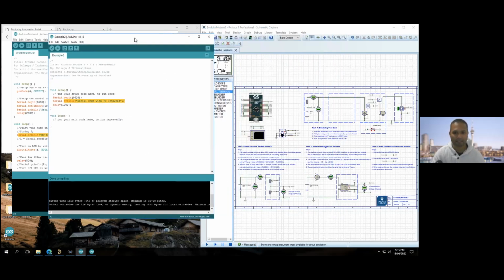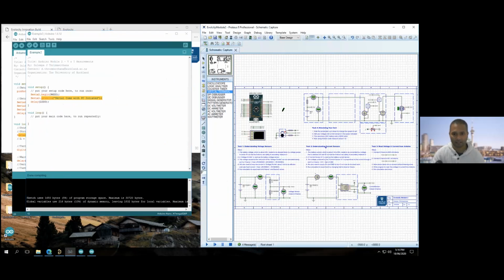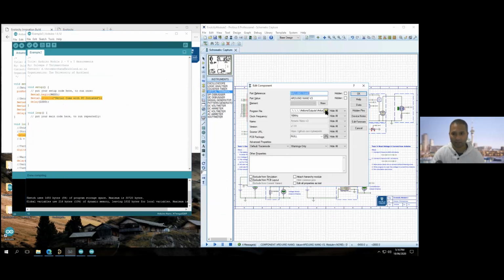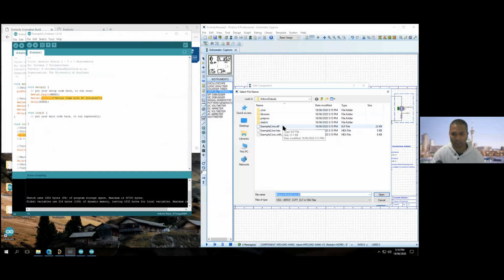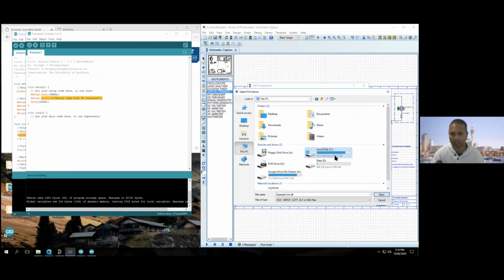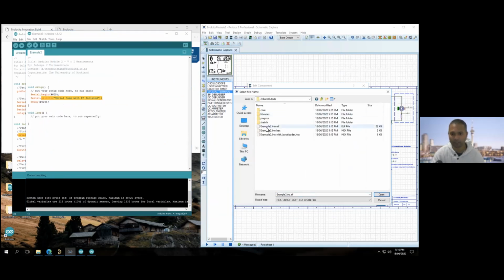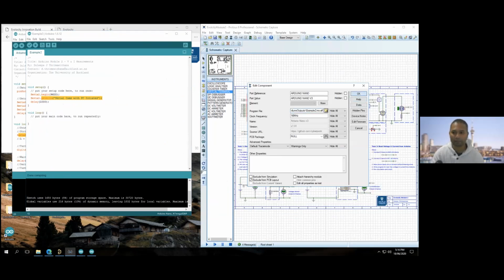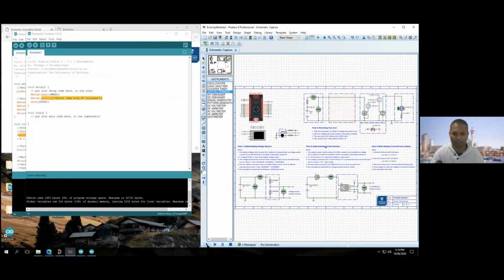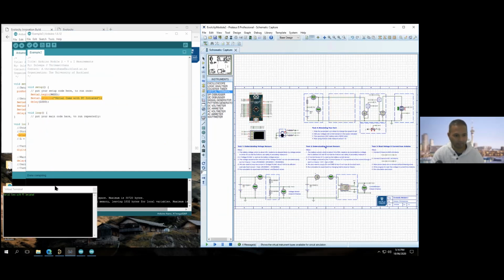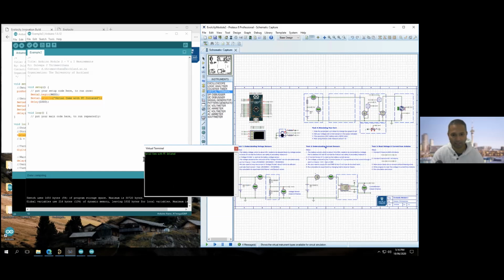And then what I can do is go into the Arduino and show where the example 2 is. Again, reminding you it's in the C drive. We created a folder called Arduino Outputs. It's in there. So we open that up, press OK. Now we are ready to run. So if we had done this properly, it'll show a command saying serial comms with PC initiated.